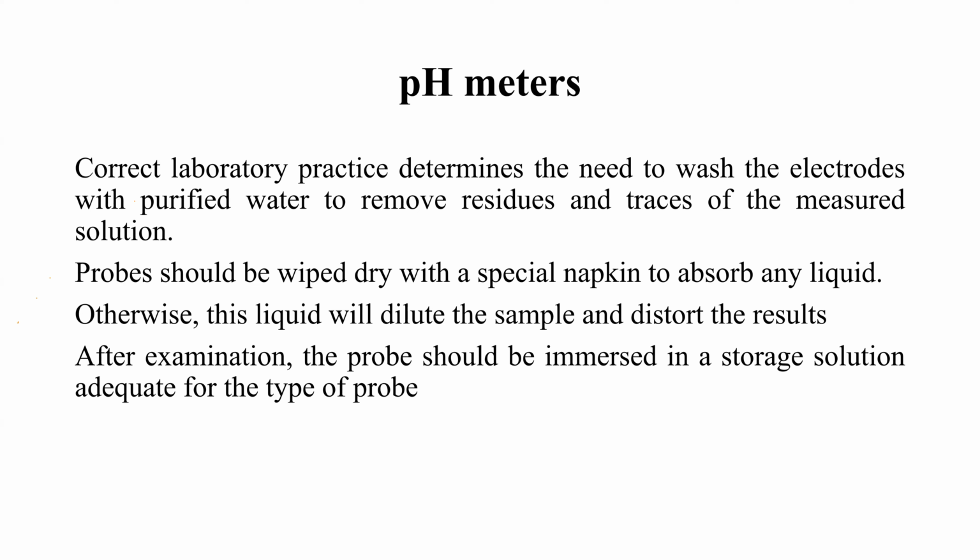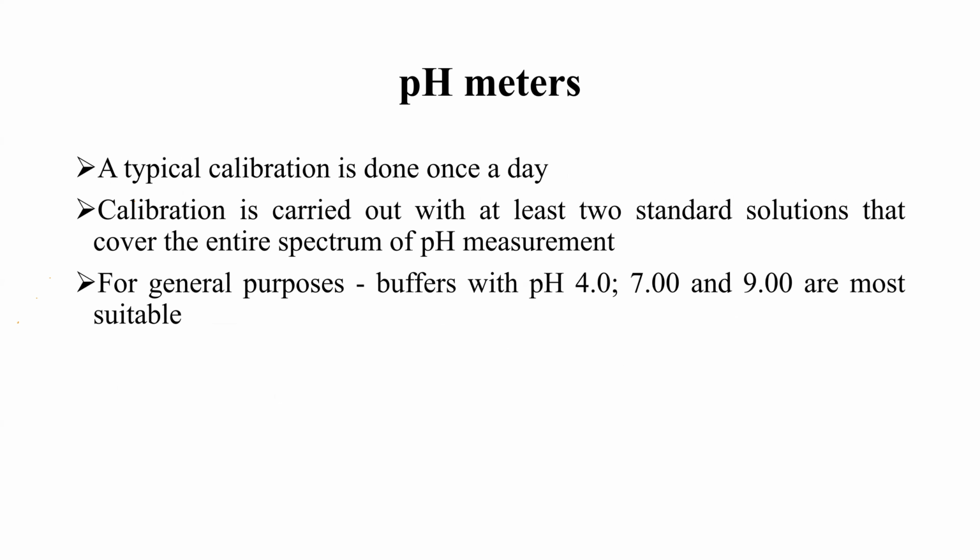We should always clean the probes and electrodes and wipe them dry, and keep the electrodes in a special solution, usually 3 molar potassium salt, potassium chloride.